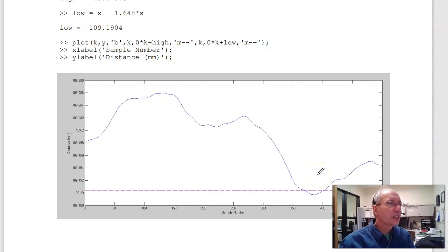So that is homework set number 11 for ECE 376. This is one of the reasons we study Z-transforms. If you want to filter some data on a microprocessor, you really should be using Z-transforms. You have a difference equation, you've got data at discrete time points. Difference equations are much easier to implement in code. And it's identical, equivalent to the S-plane, but the Z-plane is how you implement it. For me, S-plane is how I analyze it. Homework set number 11 for 376.